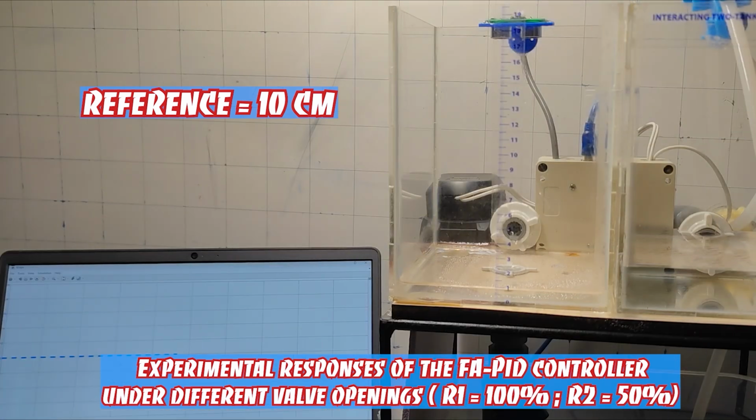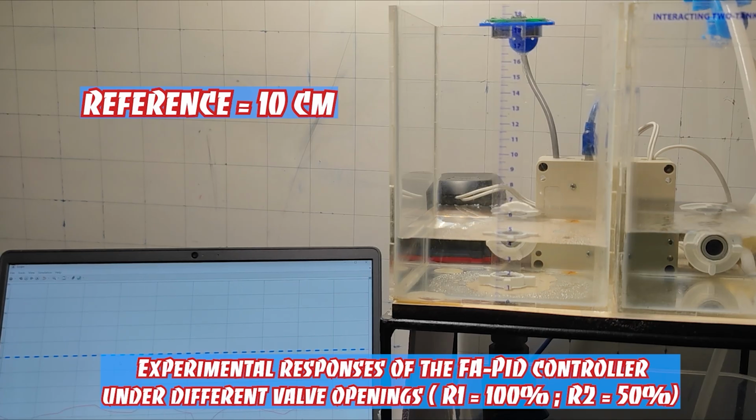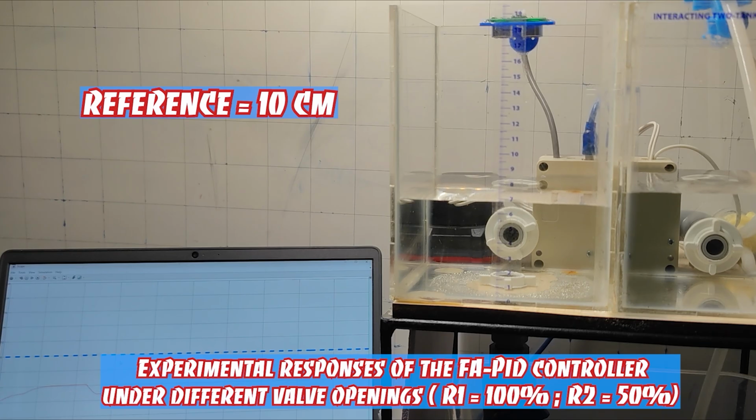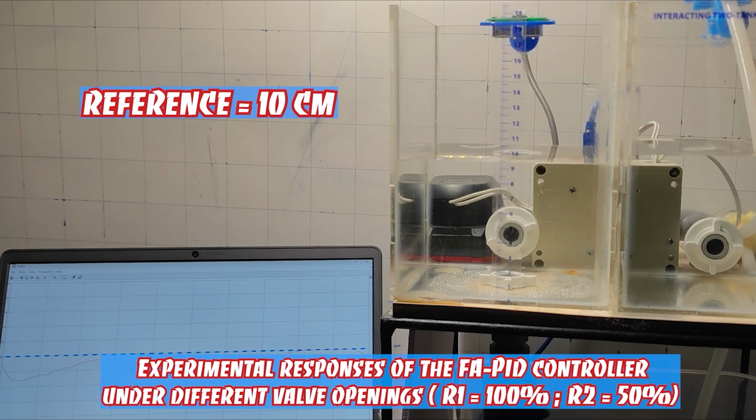In the second experiment, I increase valve R2 by another 25%. You can see that the water in tank 2 starts to flow faster. This can be observed through the water levels in both tanks. In the first experiment, the levels of the two tanks were almost equal, but in this second experiment, the water level in tank 1 is slightly higher than in tank 2.